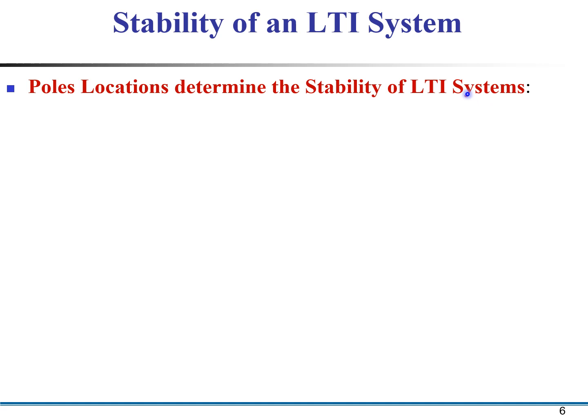And when I am saying the pole of the system, as we studied on the previous slides, G(s), the system transfer function, is N(s) upon D(s). Then the zeros of this polynomial, which we also call the characteristic polynomial, are the poles of the system.